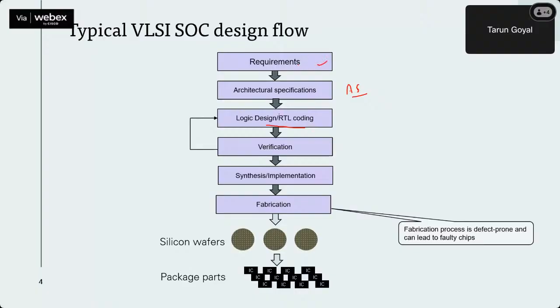Okay, once we have done the coding, then let's say we have reached the end, at gates, flip-flops and all whatnot at that level. Then it comes to verification. We verify, suppose we have designed an adder, whether the adder is working and giving me the correct three-input adder. That's the kind of test bench environment we write to verify and ensure that yes, the particular application we are able to get. Then once we have a good RTL which we require, we go for the synthesis and implementation.